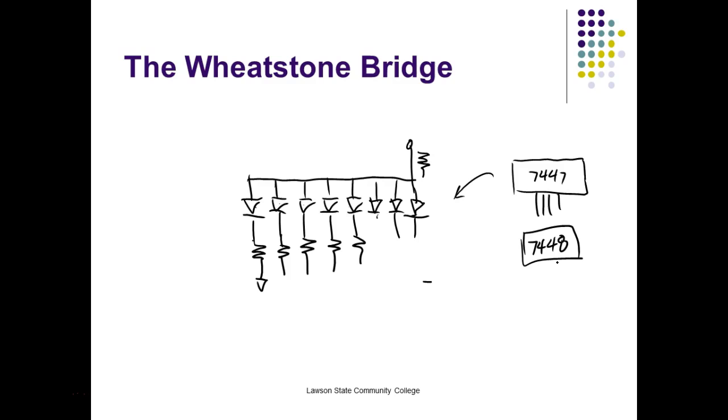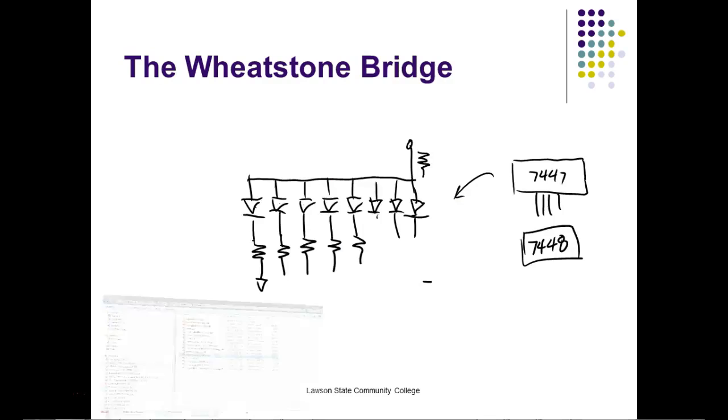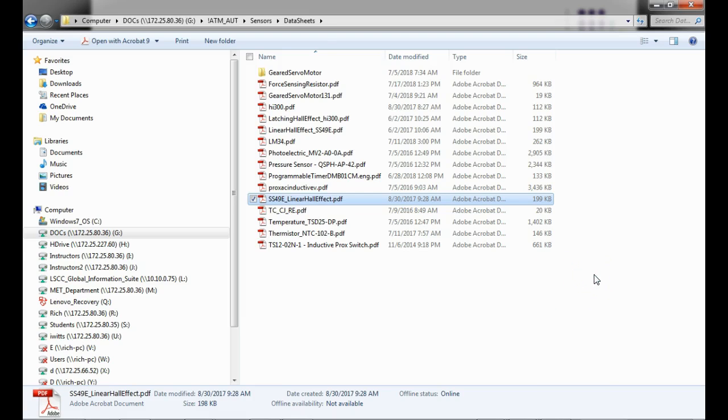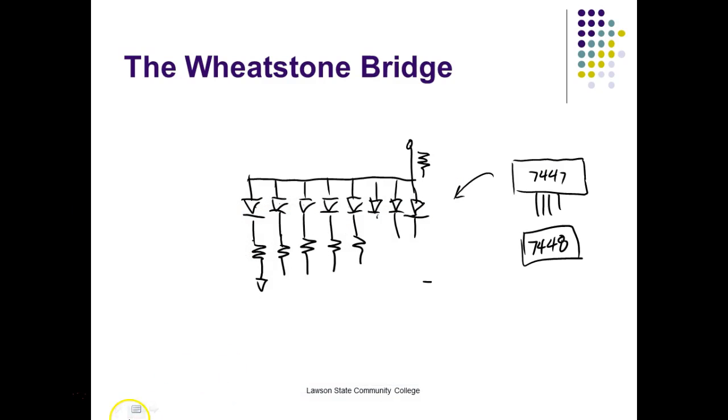And that's the way you buy them. So if we go to a site like Jameco and look, they're going to be called CA, and CCs are going to be what? Common cathode. CAs are going to be what? Common anode. And then it might have LH. What does LH mean? It means it would have a left-hand decimal point, right?